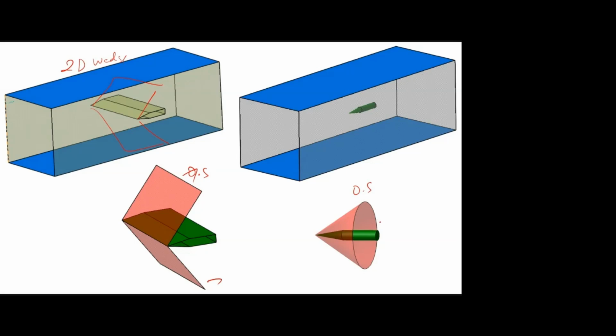Yes, sir. And if you compare this beta, this 3D will produce less beta. So for example, they mention if theta is 20 degrees and Mach number is 2, here they are getting 57 or some 53 something. Here they are getting 37 degree beta. Okay, so this is what they observed.